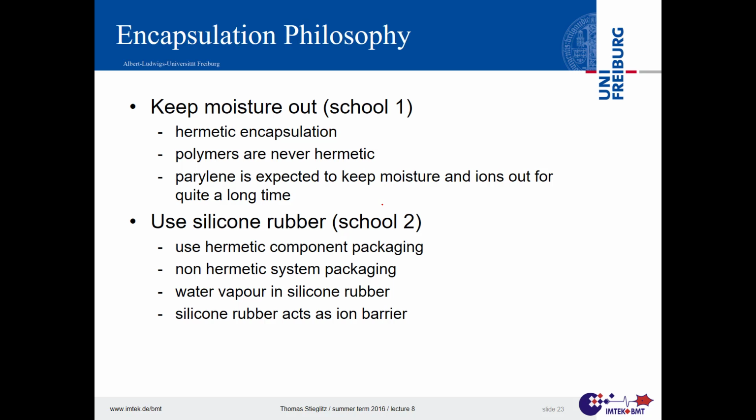So this is what I told you now 3 times in written words. Keep moisture out, or use silicone rubber, and then you get moisture. But it doesn't matter if you get moisture if things stick together. Then it works. But this is still a non-hermetic encapsulation.